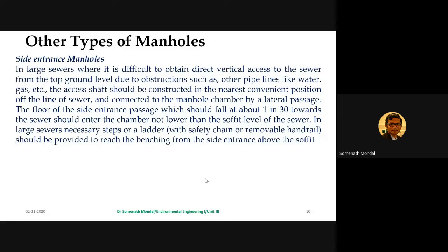So if you have a step, basically what is happening is you are coming from the side. So if the level of your side entrance and the level of your bench are not the same, in that case you need to provide some ladder or some steps to reach the bottom. So with this, we'll stop today's class, and in the next class, we'll discuss other types of manholes and subsequent appurtenances.